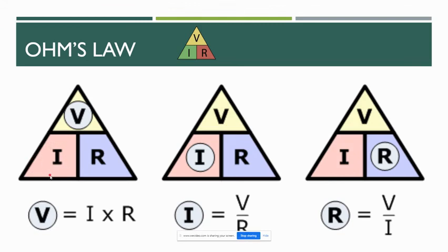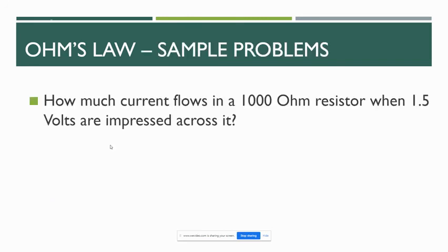I have to reduce that, because 100 milliamps is the same as 0.1 amps. So I have to use the 0.1 here. As another example, if my resistance is 10 k ohms, that's 10,000 ohms. I have to use the 10,000 number here, not 10. Again, you have to remove the modifiers before you use any of these.